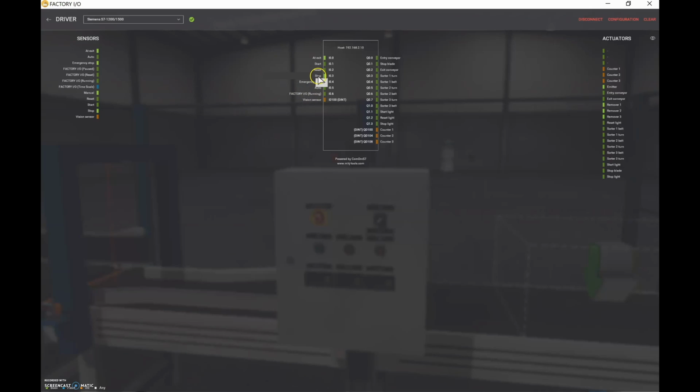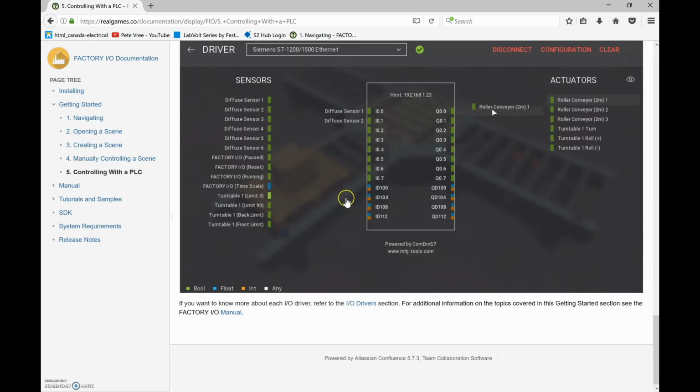But say I wanted to get rid of this guy, I could take the stop and bring it back over here and get rid of it, right? And I could move some things around. But based off of this program, the stop is connected into input 03. So I'm just going to drag it over and drop it in. And then we're ready to rock and roll. Okay, looks good.